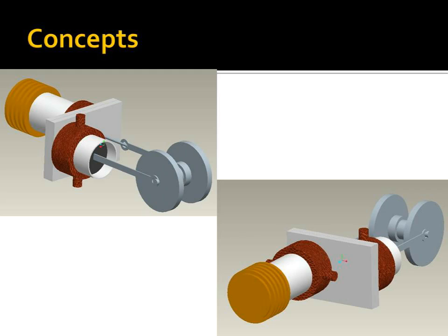Ideally, I'd like to have a displacer piston made out of Pyrex glass, because the overall objective of the regenerator is to have low thermal conductivity, low fluid friction losses, and low weight. Pyrex glass would be ideal for this. However, I'd need to get it specially ordered. So I'm looking into alternatives. A very funny one, and I'm not sure of how it's going to work.